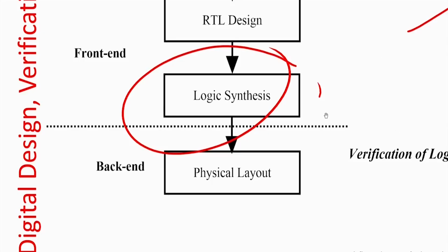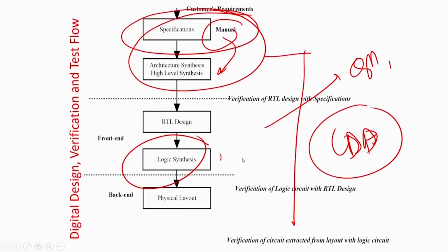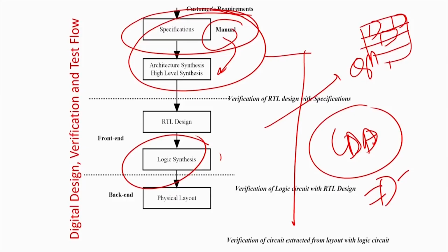Then finally there is something called physical layout. Physical layout means the gate level will be implemented in terms of hardware, transistors. In that case also you should have very good placement and routing algorithms, because in placement and routing, you have the circuit die and you have to put your gates in all the places and make interconnections. When you implement, a gate will not look like this; a gate will look like a rectangle, and there are a lot of rows in a die. You have to put the gates in the proper positions in a minimal amount of area so that you can do the interconnection.